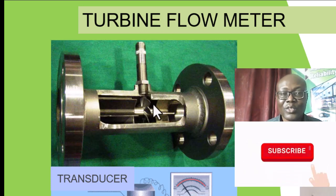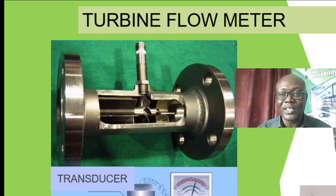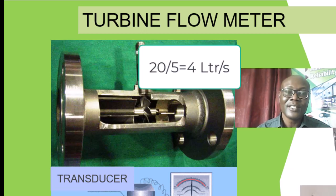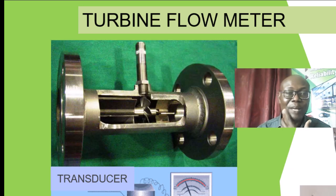Okay, so the time it takes for us to generate those 10 pulses, assume it is 5 seconds. So that means we'll have 20/5. Okay, that will give us 4 liters per second. So that will now be the flow rate through that section of the turbine.